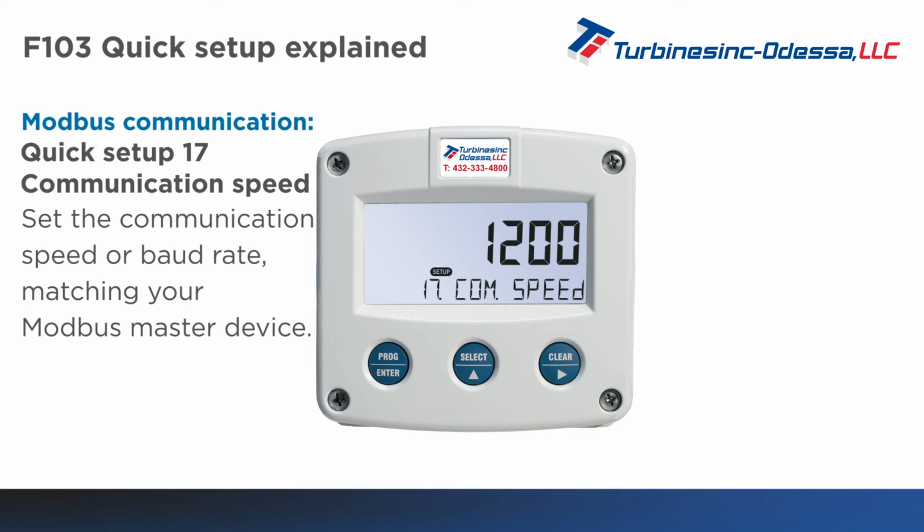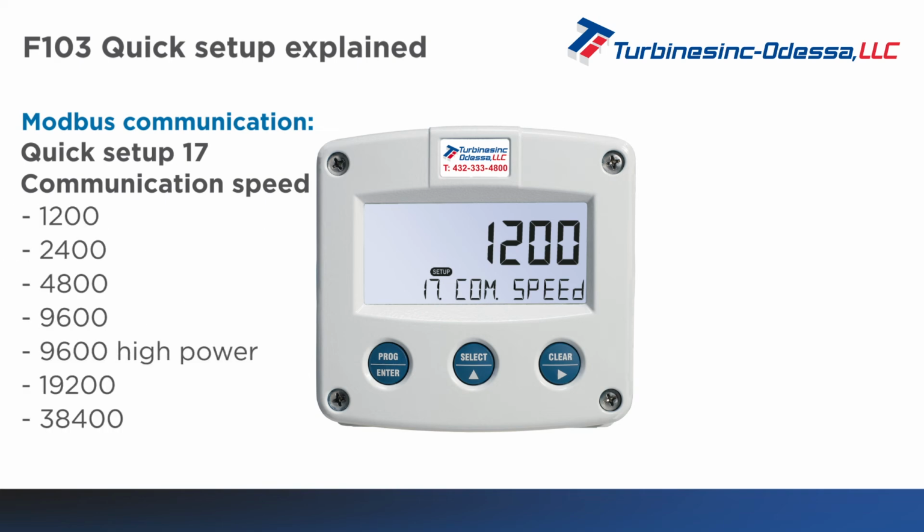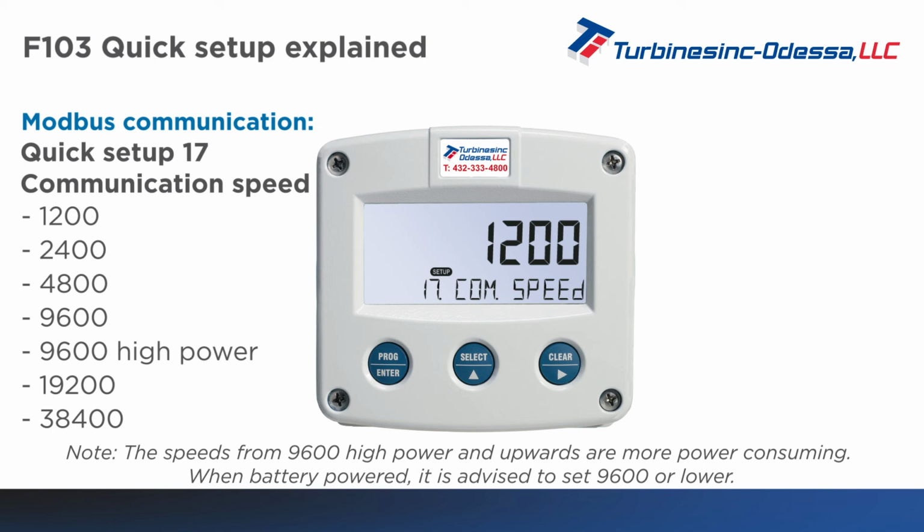The following speeds can be selected: 1200, 2400, 4800, 9600, 9600 high power, 19200, 38400. Note, the speeds from 9600 high power and upwards are more power consuming. When battery powered, it is advised to set 9600 or lower.